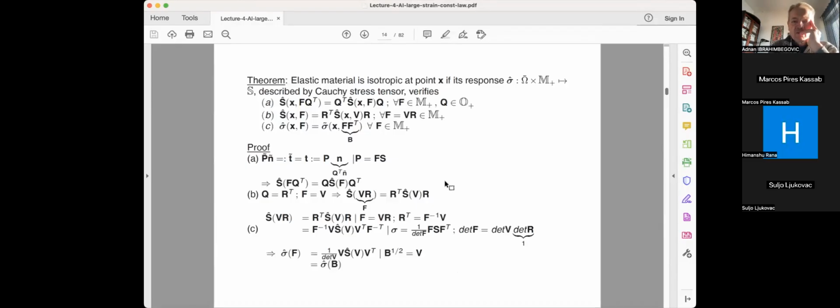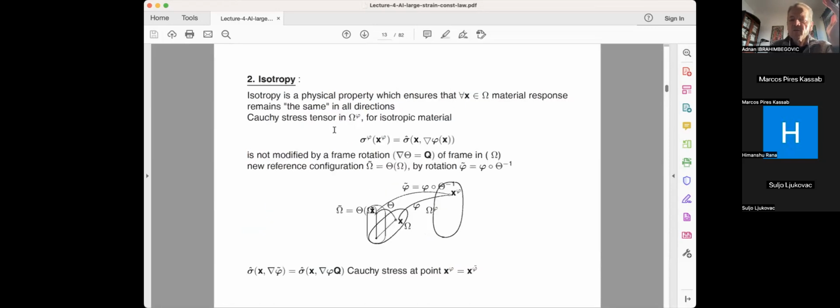So here you have a similar but somewhat inverse situation. If I really want to express the constitutive model, it has to be expressed in terms of the second Piola-Kirchhoff stress, which is a function of F, and the orientated configuration, which is obtained as the deformation gradient times Q transpose. Again, Q is an orthogonal tensor, which gives me the simple rotation of this initial configuration.